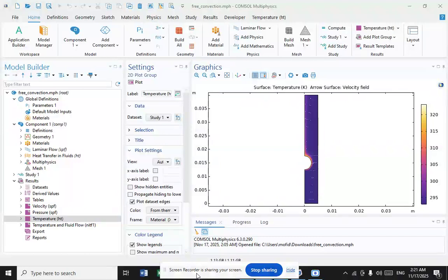In narrow and closed cavities, free convection flow is much more complex due to the interaction between near-wall fluid flows formed on the heat exchange surfaces. On heating one vertical wall at temperature Th and cooling the other at temperature Tc, modes with a common fluid flow through the entire cavity are possible that involve local secondary flows near vertical walls, as is exemplified here in this simulation by free convection in a square cavity.